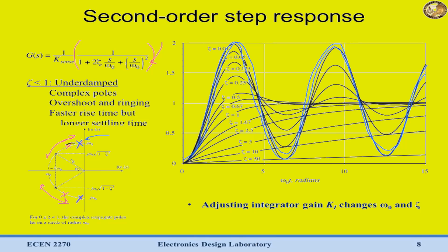As we start to move these poles down, as we start to increase the real part of them and move them closer to the real axis, and further away from this imaginary one, we can start to reduce the magnitude of this ringing and have our system settle to its desired reference value faster and faster. Now eventually, if we move these poles back far enough, they're going to hit the real axis. And let's take a look at what happens when we're there.